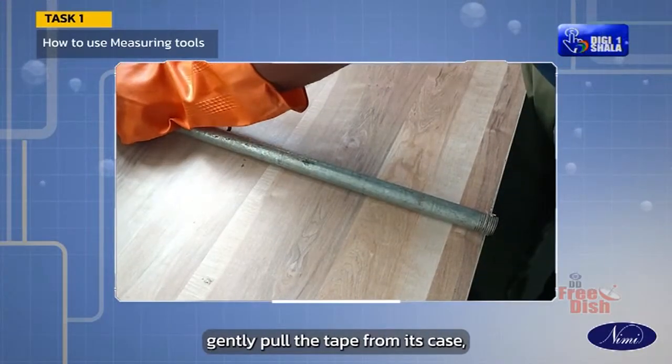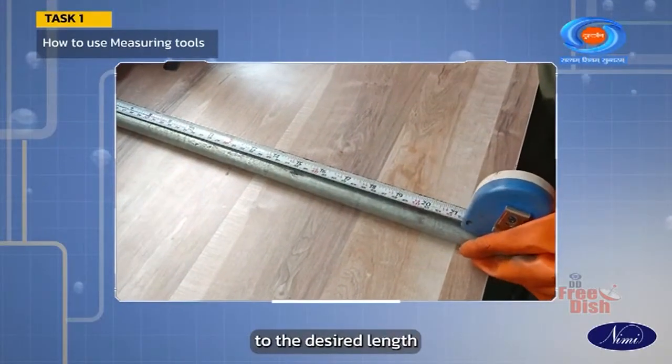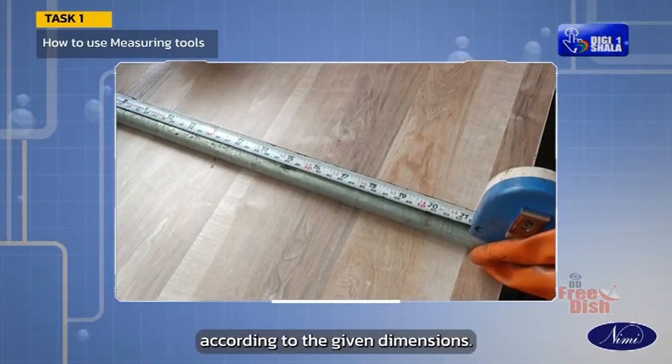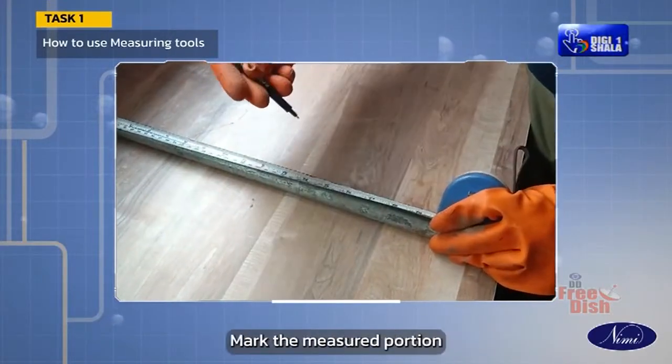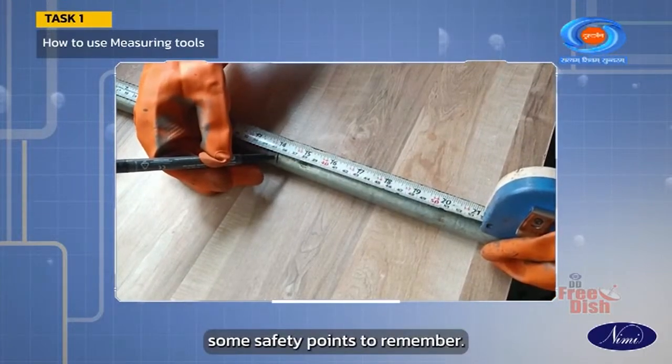Steel tape. Gently pull the tape from its case, guiding it from the starting point to the desired length. Measure according to the given dimensions. Mark the measured portion. Some safety points to remember.